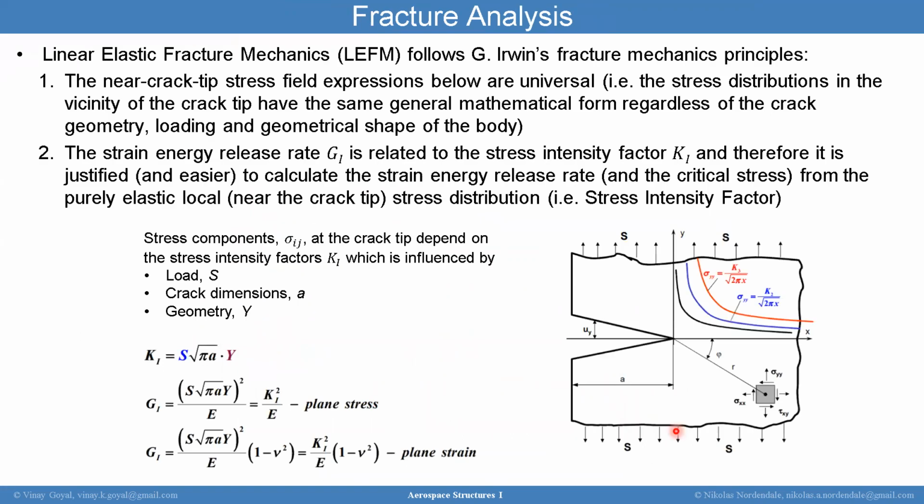Linear elastic fracture mechanics is an approach to characterize the stress intensity factor, the stress intensity at a sharp crack tip. A crack tip is going to have infinite stress, so you have to find a way of predicting failure. A flaw typically will result in infinite stress, and so therefore you need a way of assessing that. One approach is to use the near crack tip stress field expressions. And then here's an example of that.